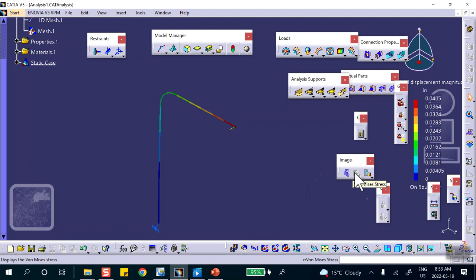There is an area. The radial cross-sectional area, I gave it. It knows what the area is. But let's move on. You're on the right track. But if I ask you, what is the stress in this beam? What would you tell me? Stress where? If you go back to your stress analysis class, the stress was linear. At the neutral surface, for beam bending, the stress was 0 if it's pure bending. And it gradually grows. Biggest on the top, biggest at the bottom.